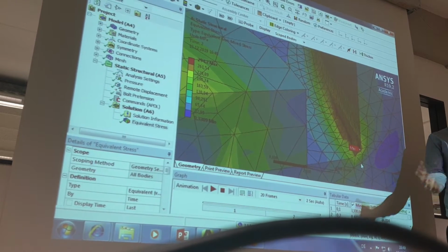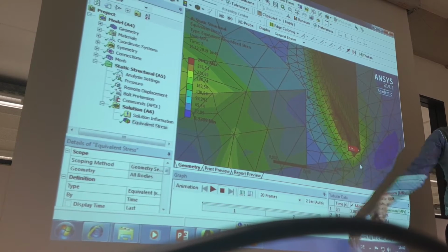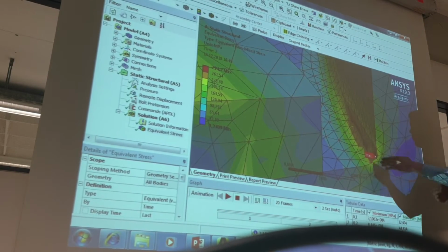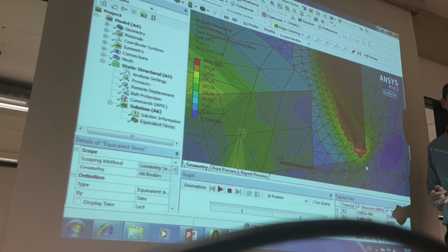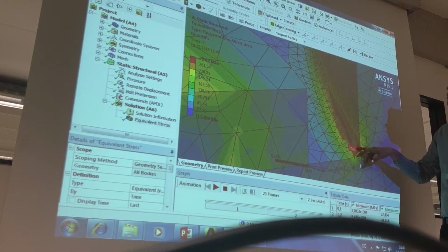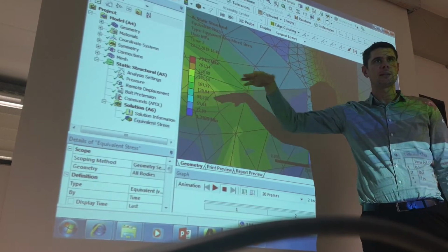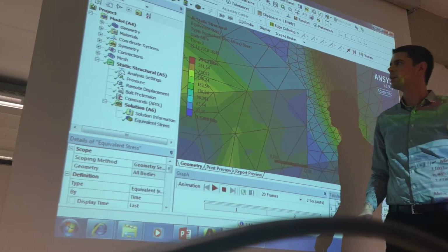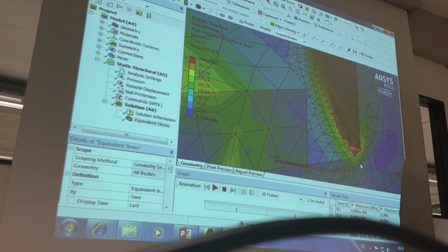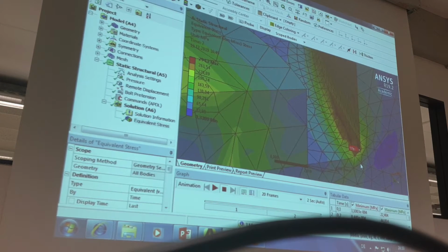And if I do it now with tetra mesh, then I have 300,000 nodes. And then I need to wait 2 hours, or 3 hours, to get good, correct results. And you will get good results with hexa mesh in 8 minutes maybe. So this is a problem, but I see where the dangerous place is, and I see, okay, 290 megapascal is the maximum stress. But with hexa mesh, you will see here 320 or I don't know. So much more stress. So, okay, our simulation is finished.